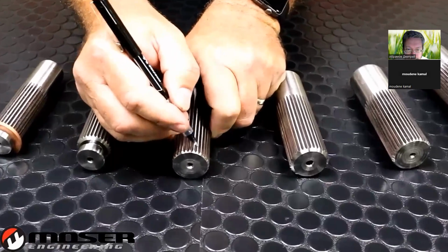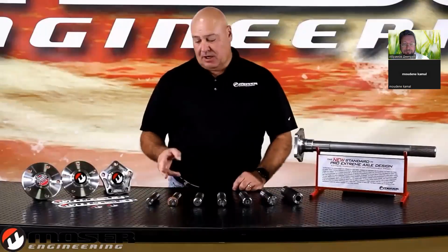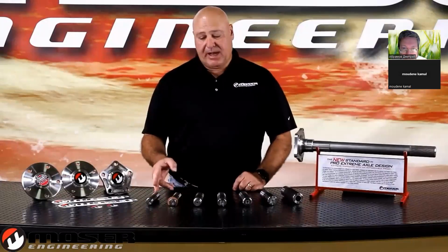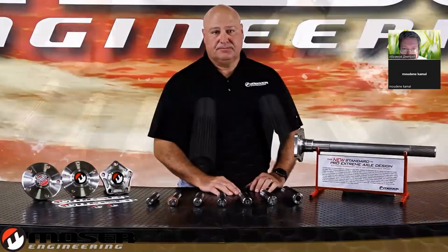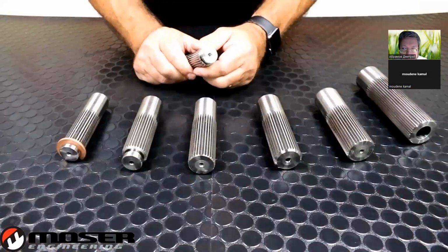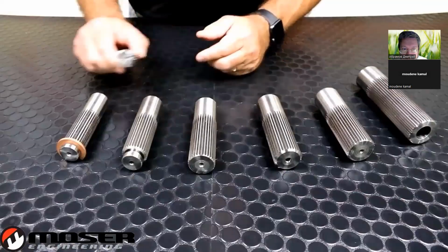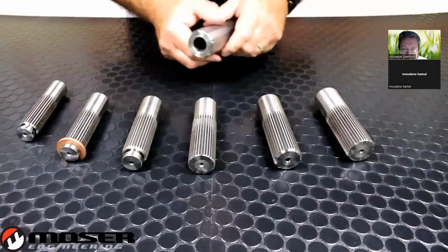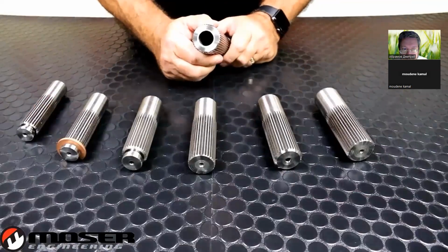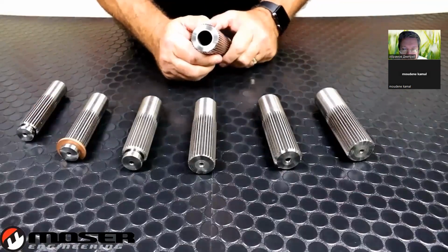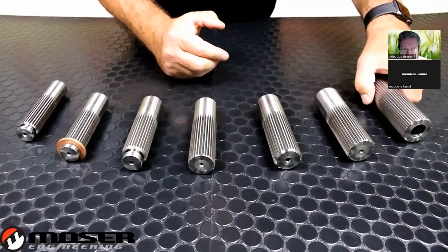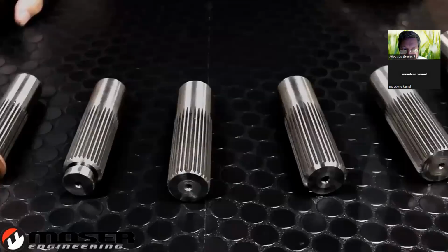on the axle. Here in front of me, we have some of our most popular axle splines, starting with the 26 spline C-clip axle and progressing all the way up to our 40 spline race axles. This is our 26 spline OEM replacement axle. It measures just over 1 inch in diameter. This is our 40 spline, which measures just over 1 3/4 inch diameter. When you have more power, you need more spline.